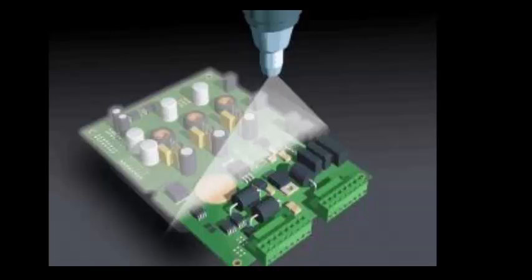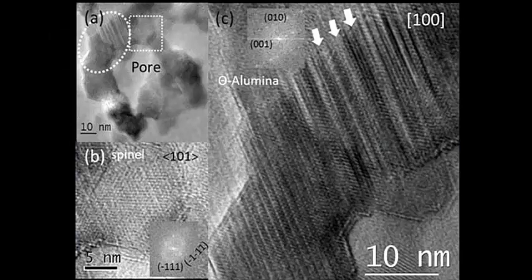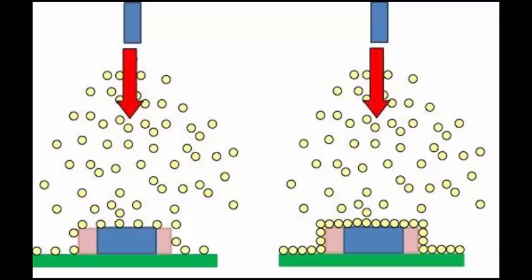Generally, conformal coating materials are applied to electronic circuitry to act as protection against moisture, dust, chemicals. And for this protection to act properly, it has to cover the whole surface. And ALD systems can be designed to deposit pinhole-free coatings that are perfectly uniform in thickness, even deep inside pores, trenches, and cavities.